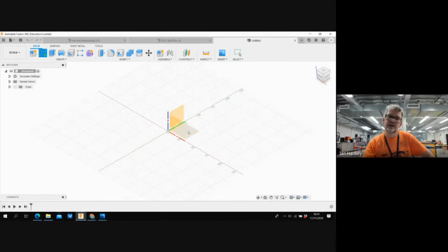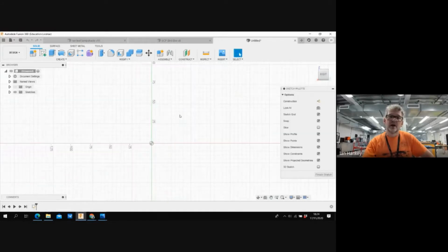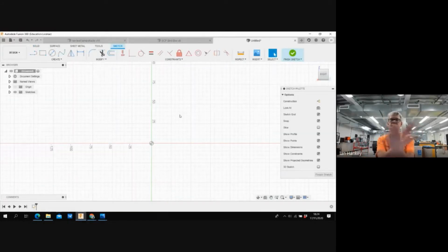I can draw on the bottom plane there, I can draw on this side one or this side one. So I'm just going to left click on that plane there. We're using a PC, by the way, so I've got left and right click. And that's offered up that plane for me. But this line down the middle is very important. This is my axis going down and another axis going across here. So I'm actually going to draw on here.